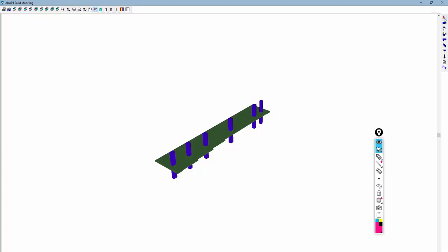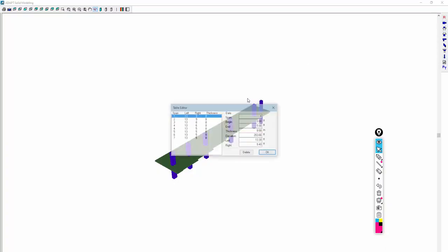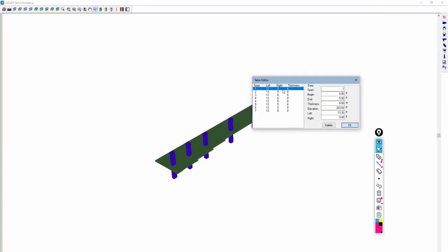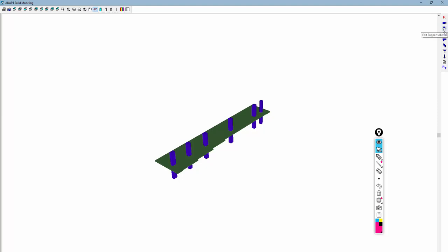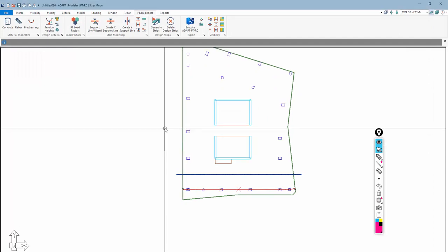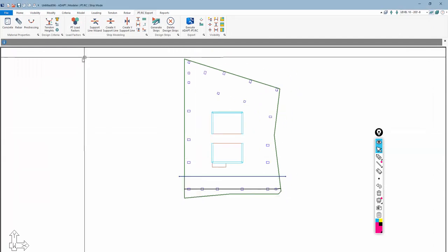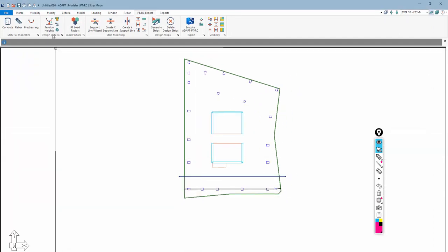You could actually use tools here to edit. So if I wanted to edit geometry of any of the different segments, I could use this tool to do that. I could use the other tools to edit supports above or below, beam cross sections if there are beams, drop caps, panels, and loads. Okay, and you could actually send this directly to Adapt PT through this button as well.